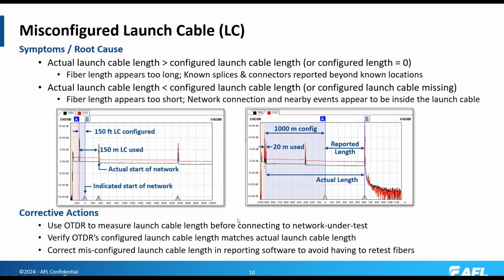You can correct misconfigured launch cables in the reporting software. AFL Flex reports will allow you to do that, so that if you did misconfigure when you ran the test, you don't have to go back out to the field and repeat the test.